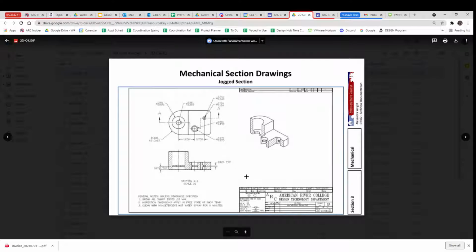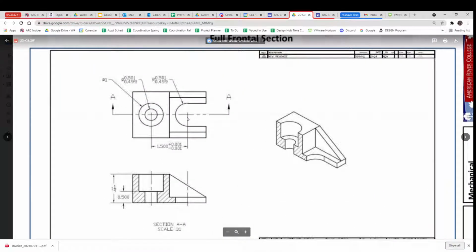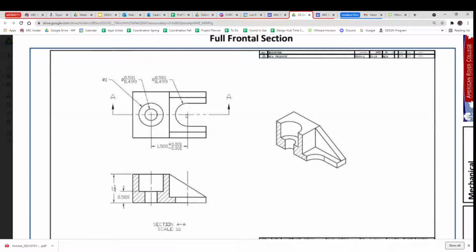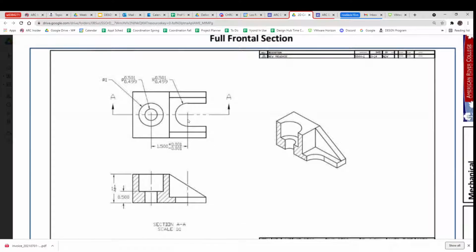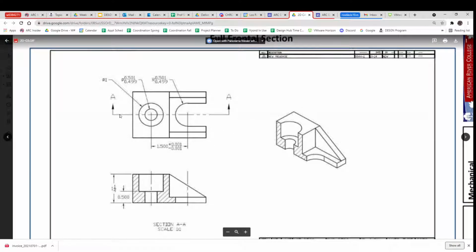Over here, this should have really had a break, because that was really a center mark. So this section line went over the center mark line, and that is not really symmetrical with that. What should have happened is that this section line was broken between here and here. When it's obvious like this, the section line should be broken here and here.